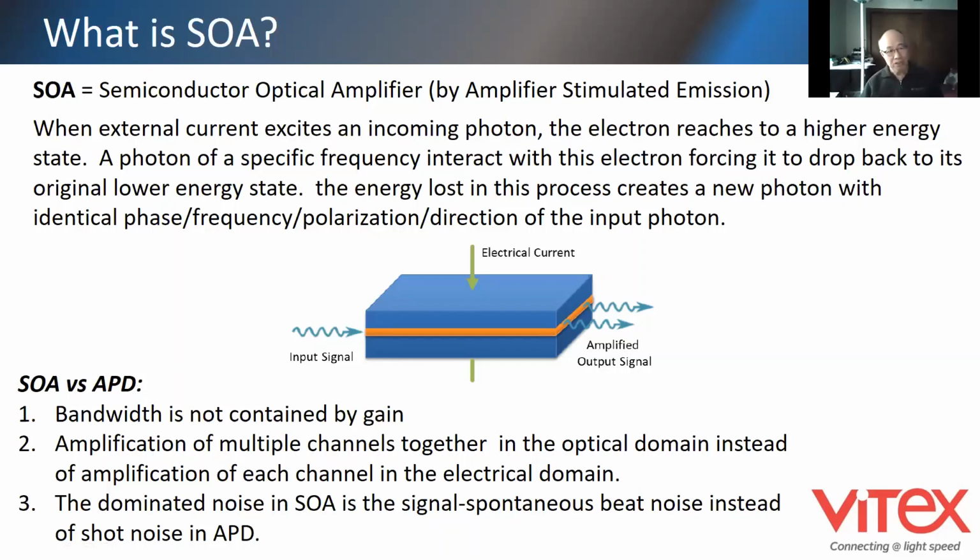A comparison between SOA and APD: first, with an SOA the bandwidth is not constrained by the gain. Secondly, you can amplify multiple channels together in the optical domain, instead of the APD, where you amplify each channel in the electrical domain. The third is that the dominant noise in an SOA is the signal-spontaneous beat noise instead of the shot noise in an APD, which I have shown is